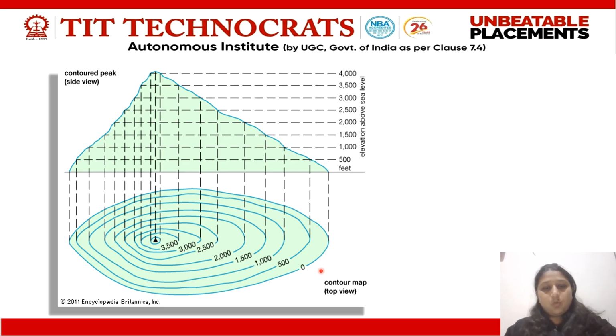Just see the contour line of 0. It is joining this point and this point. What it means is that all the points coming on this line have a reduced level of 0. Now see 3500. All the points coming on this particular contour, this circular one, will have a height of 3500. In such a way, we draw a map showing the height of various points on the Earth's surface. This is nothing but my contour map, and the lines which we use to represent the height are called contour lines.